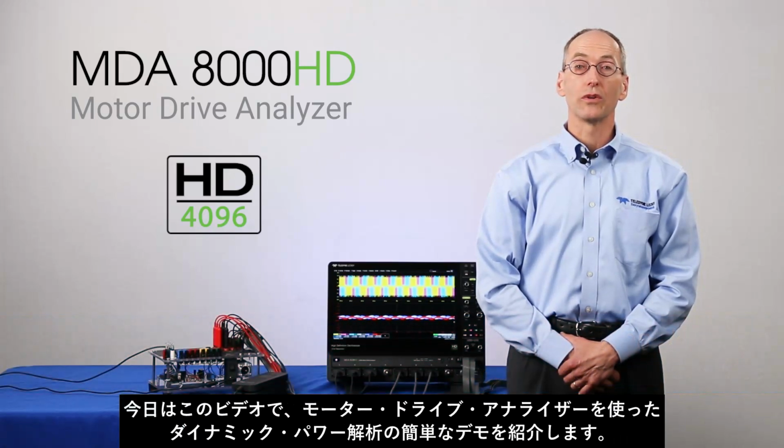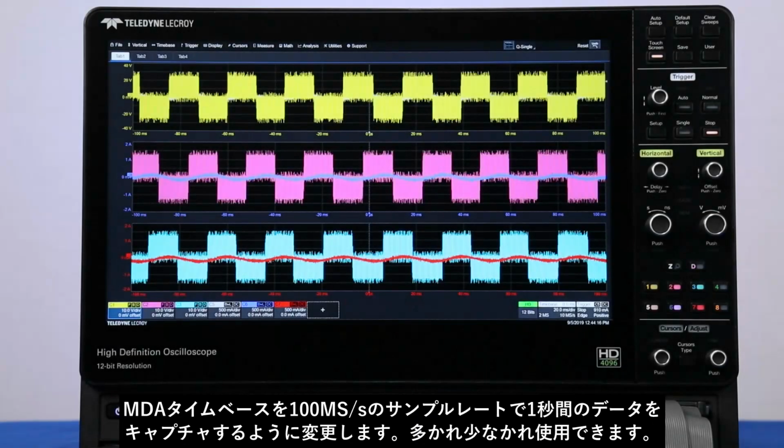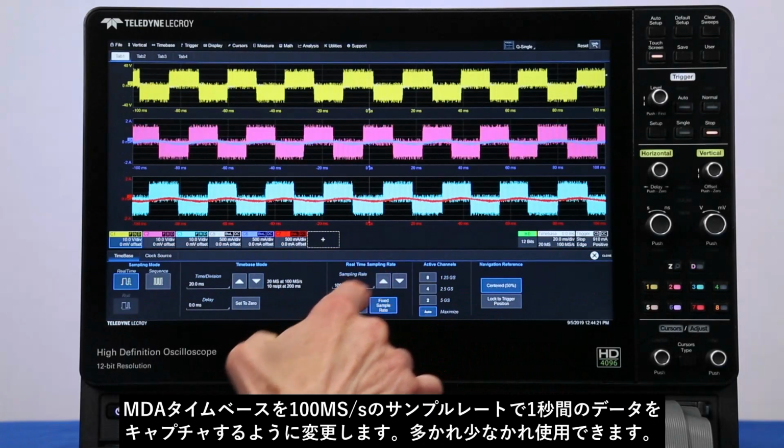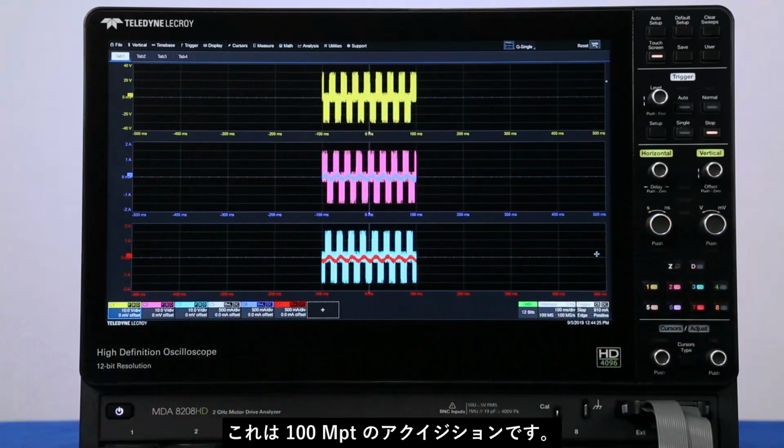Today we're going to show in this video a short demonstration of our dynamic power analysis using our motor drive analyzer. We'll change the MDA time base to capture 1 second of data at 100 megasamples per second sample rate. More or less could be used. This is a 100 megapoint acquisition.